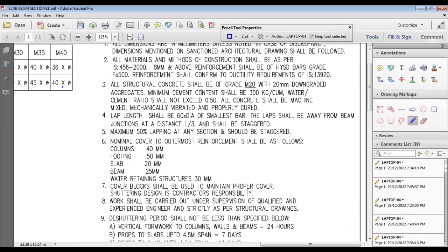Generally, if site mix is done, then the grade of concrete generally used is M20. And if you are using higher grades, then you should do the mix design from the laboratories, or you can use RMC concrete for the project. For M20 grade, people generally use site mix.